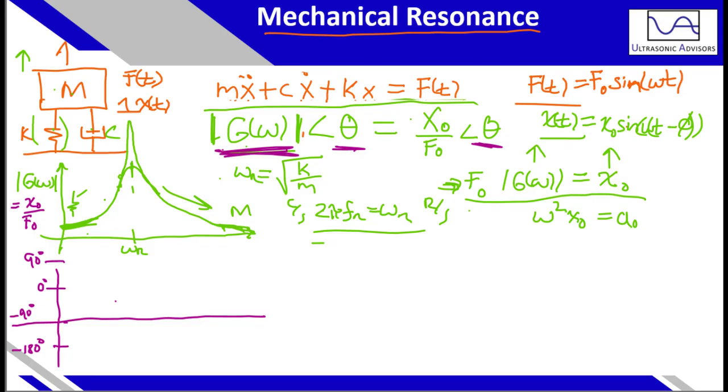So as we are starting, I mentioned at a very low frequency, your forces are exactly in sync with your displacement. So you're basically at this zero degree point right there. We're drawing the phase between the output displacement and force. So we're in phase.